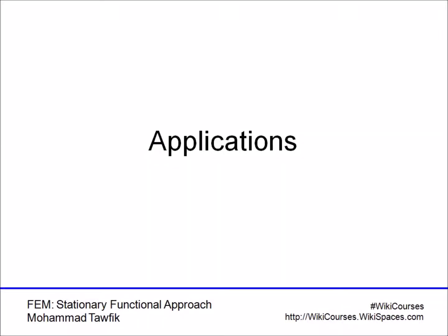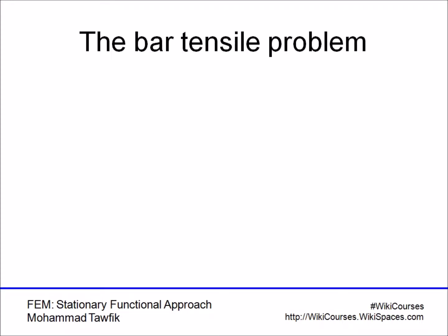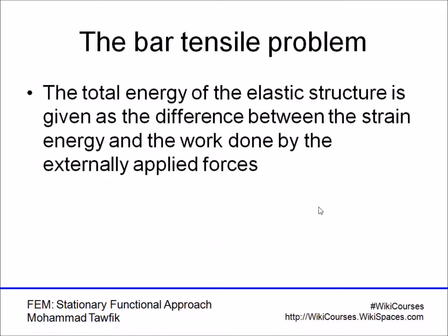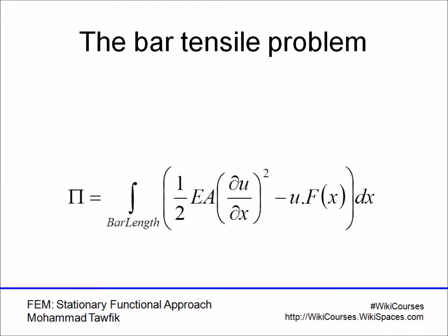Now let's use the stationary functional approach to derive the finite element model of a bar. For a bar tensile problem, the total energy of the structure would be given by the elastic energy stored in the structure minus the work done by the externally applied force.